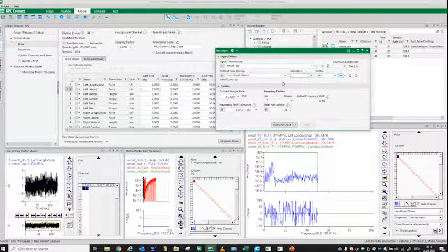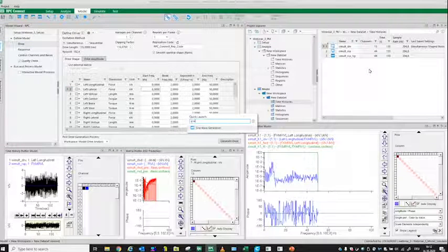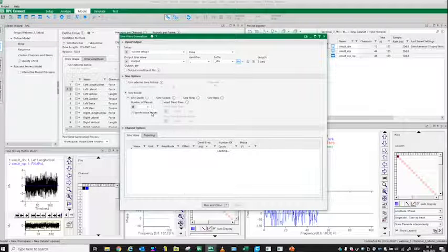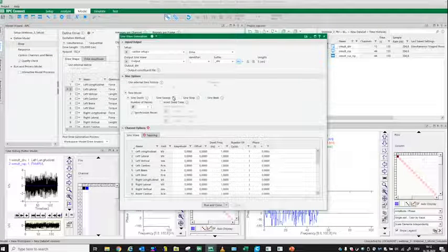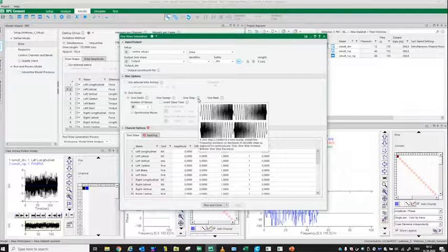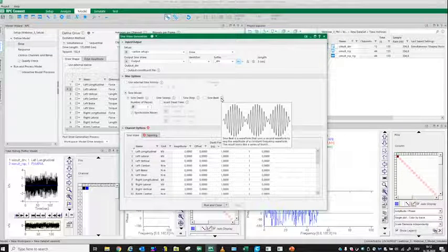And the information character, I might have shown that last time. This will show you, on different things in the tools themselves, what you are trying to type in and what you are trying to use. For example, the frequency shift: this value specifies the maximum frequency shift in the case of non-integer sample ratios. Or if we choose another tool, let's say the sine wave generation, and you want to know what a sine dwell is, it is shown here, telling you what you are going to type in. And these kinds of information characters you're directly finding in each tool or throughout the whole software.